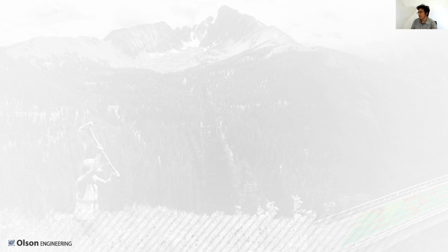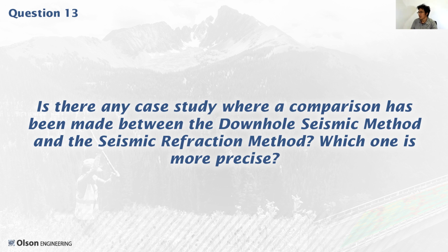Okay. Is there any case where a comparison between downhole method with refraction method, which one is more precise? So you're able to gather more information with a downhole method. But it depends on what you're asking. Because you can do refraction surveys where you have a string of geophones or hydrophones down a well. That is an ideal situation, especially if, say, you're trying to image the extent of a karst.